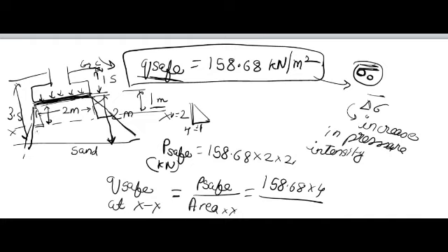So for 1 it will increase 0.5 here, and it will increase 0.5 here, and in between it is already 2 meters, so it becomes 3 by 3. The Q safe at xx is nothing but 70.52 kilonewton per meter square. Okay.